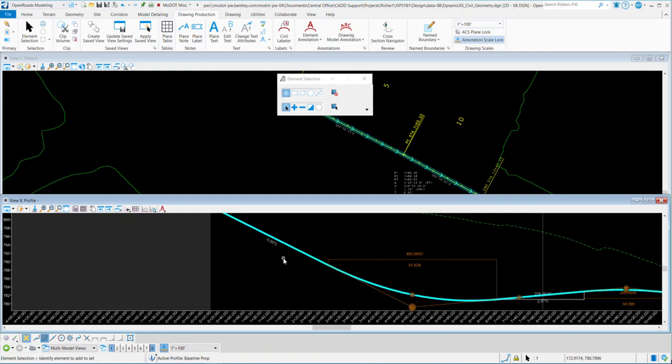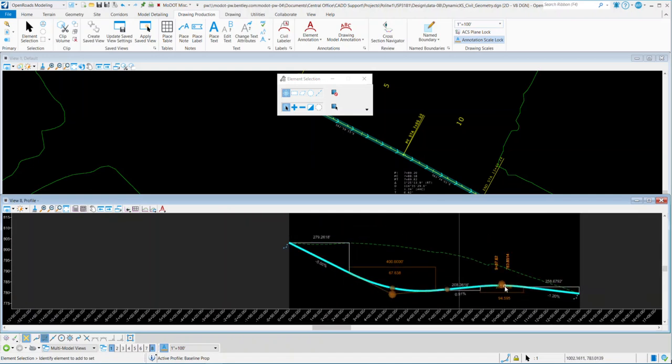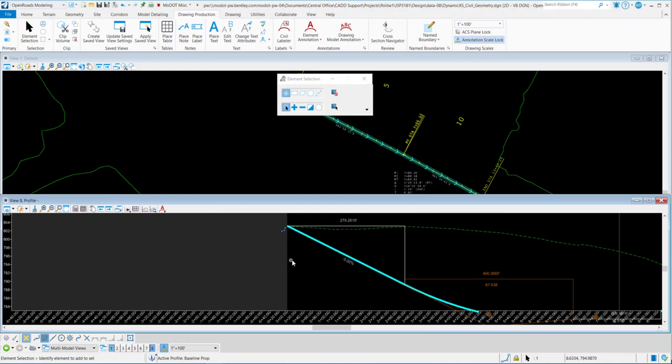Now the way this works with this tool is if it's orange or brown, you can modify it. If it's white, you cannot. So what you have to do is click in a blank area, click the alignment again, then right click over the number that you want to modify. Then it gives it to you. Then it's brown, orange, whatever color. You can select it, and we'll make it a -4%.